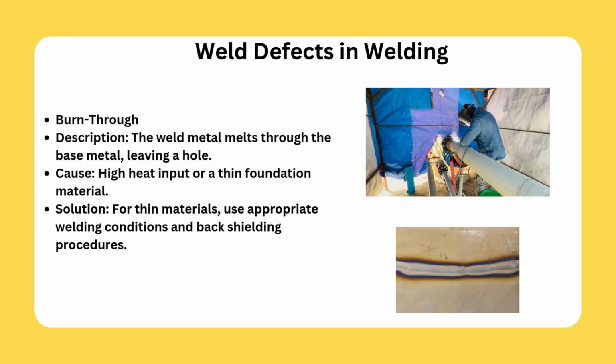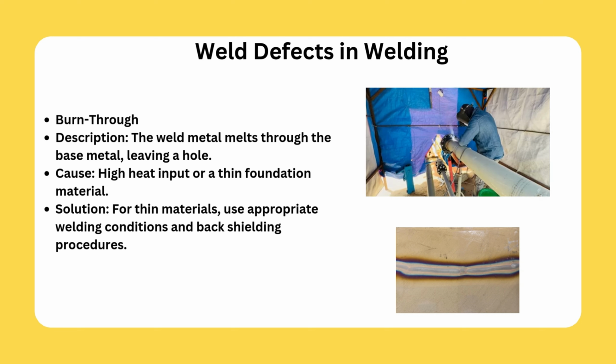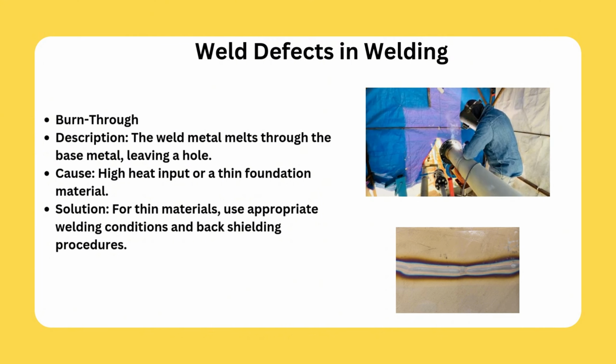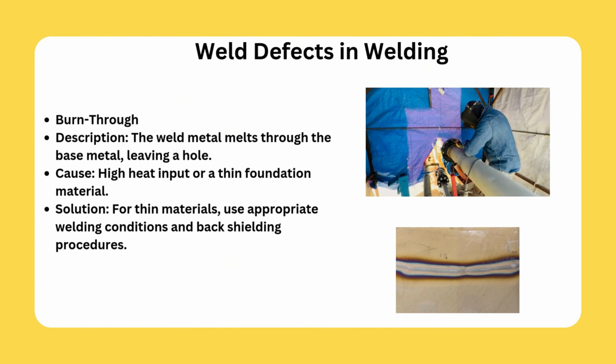Burn through. Description: the weld metal melts through the base metal, leaving a hole. Cause: high heat input or a thin foundation material. Solution: for thin materials, use appropriate welding conditions and back shielding procedures.